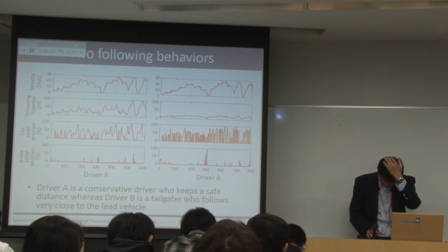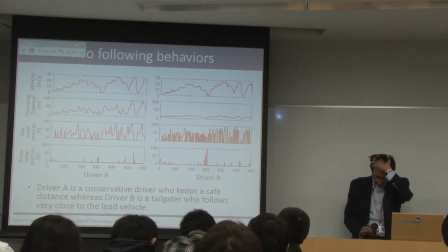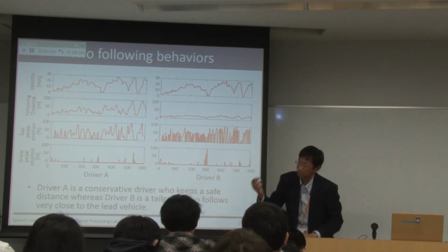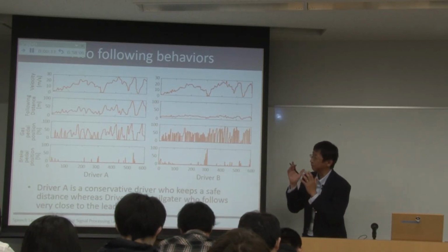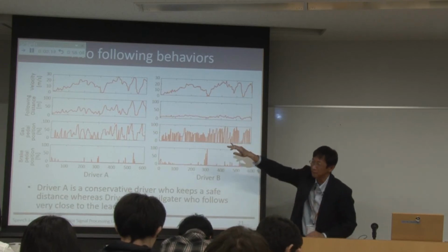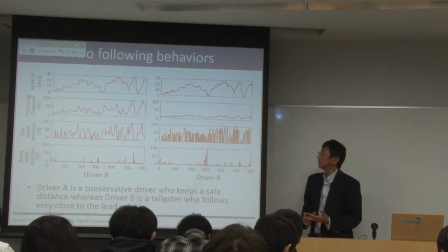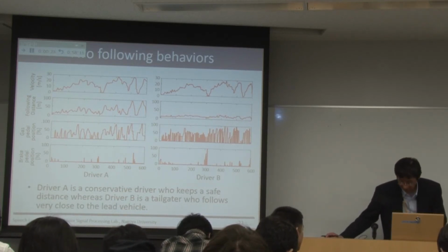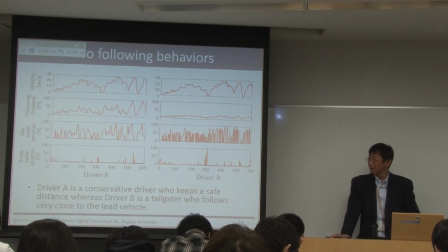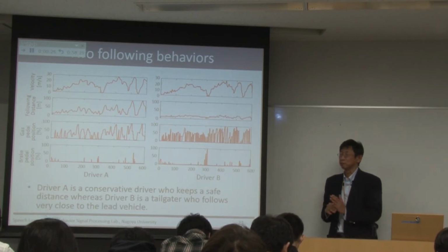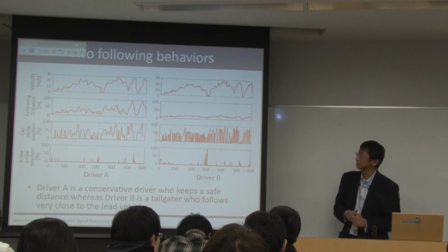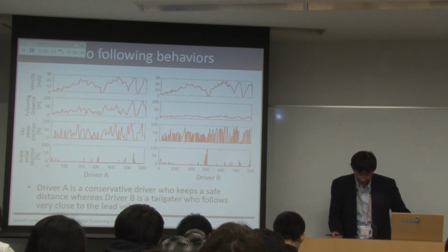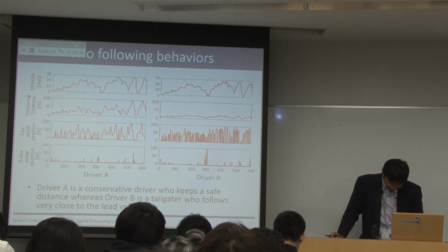So this is an example of our result, which utilizes the joint distribution of intervehicular distance and its velocity or pedal position, and estimates the pedal position 1 second later by utilizing the joint distribution and maximizing the distribution, selecting the maximum probability value as the prediction result.